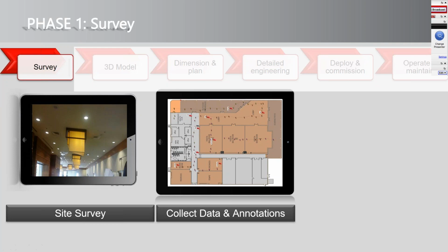And this is interesting because many people have to test all the candidate locations when they're doing a design. With iBwave, you can just place an access point at one or two locations, do a walk test, collect data, and then use that data, as I mentioned, to calibrate your propagation algorithm. Once you have a calibrated propagation algorithm, you can use that multiple times throughout your design.